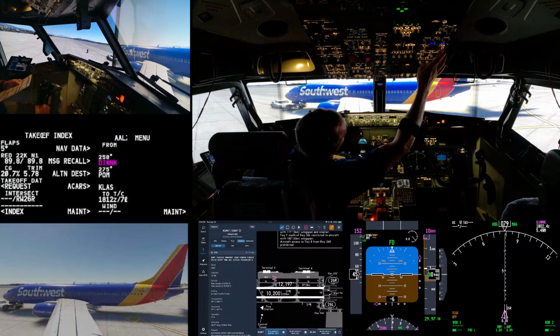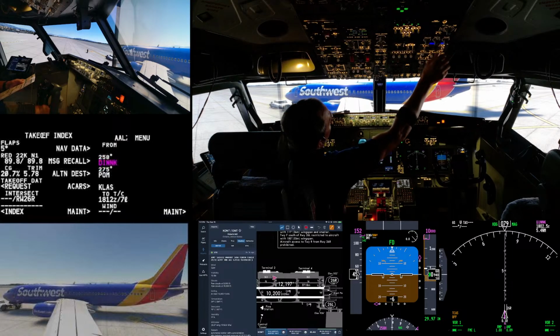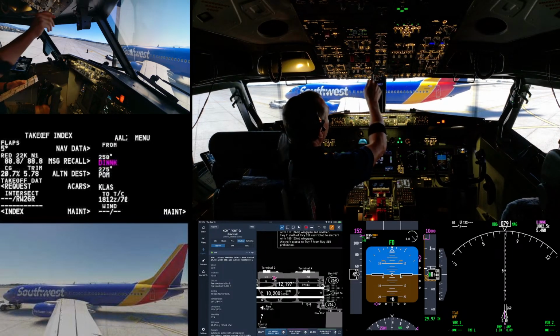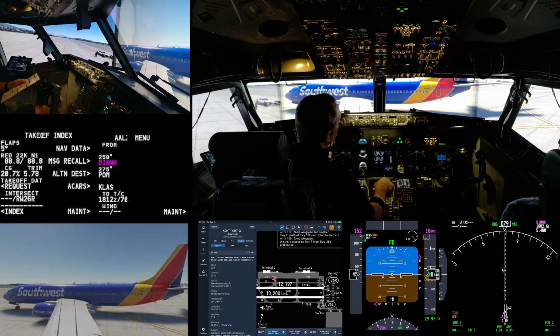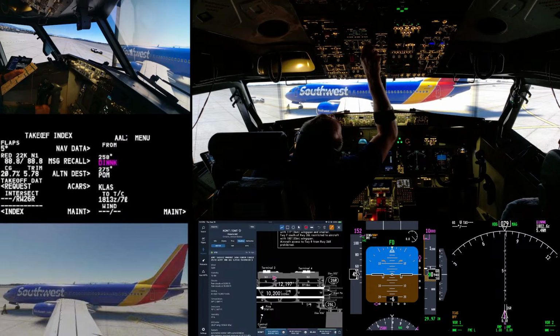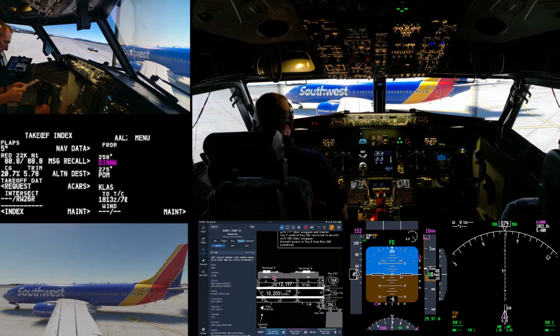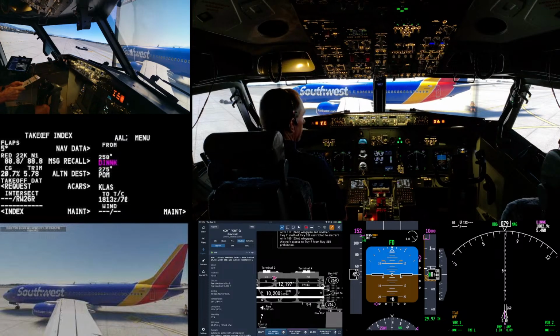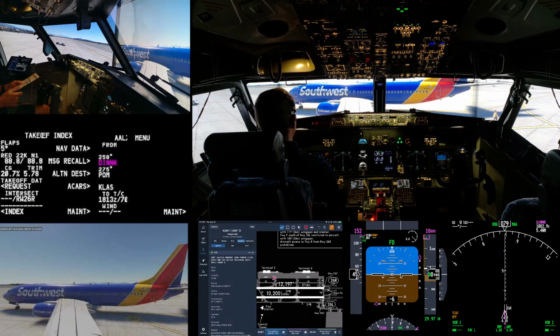I'm going to do a quick wing body overheat check. Confirm that's good. Put our packs back in auto and kill the APU. That's good. Anti-collision lights are on. Generator on the electrical bus looks good. No problem there. Bleed airs are set. APU's off. Master caution recall. Confirm. Flap set T5. Right is clear.